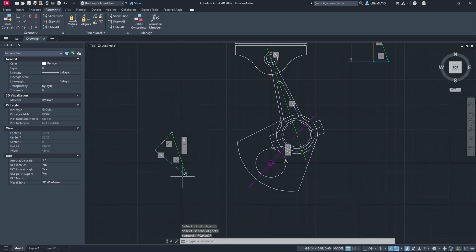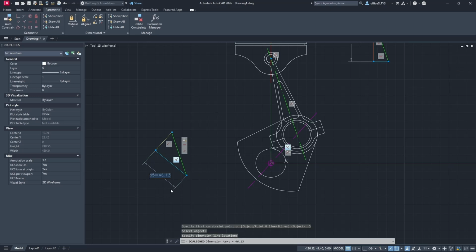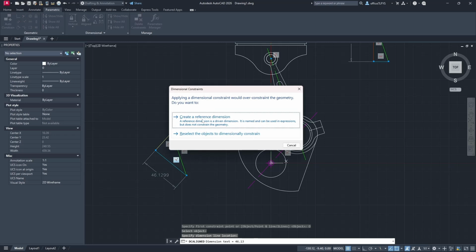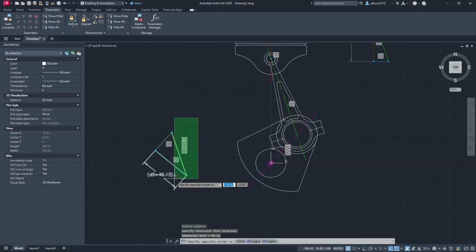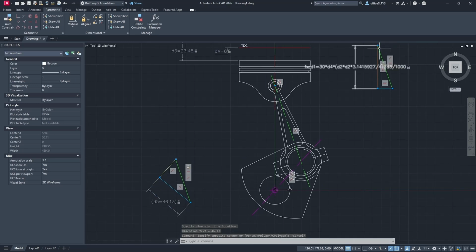What's interesting here is the magnitude of this force, which will be expressed as a dimension. However, this dimension is a reference value. It's a result, not an input. It is derived based on the piston position and the formed triangle, which gives us the resulting force here.